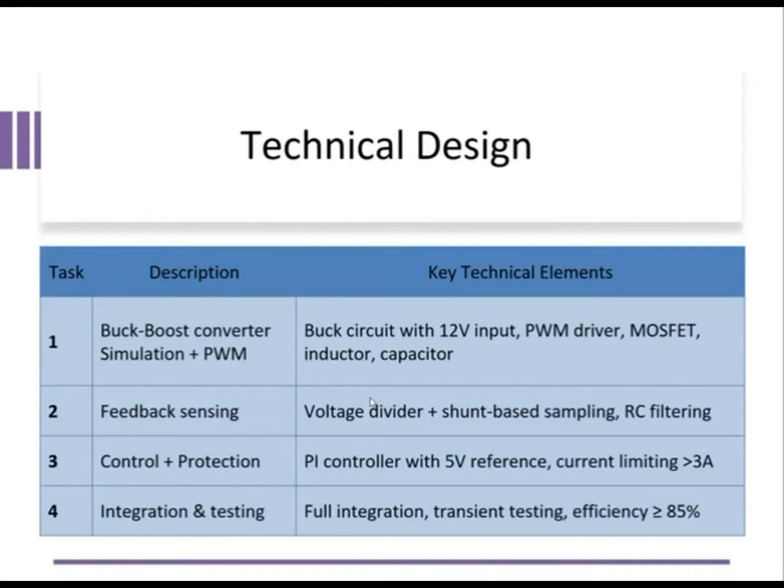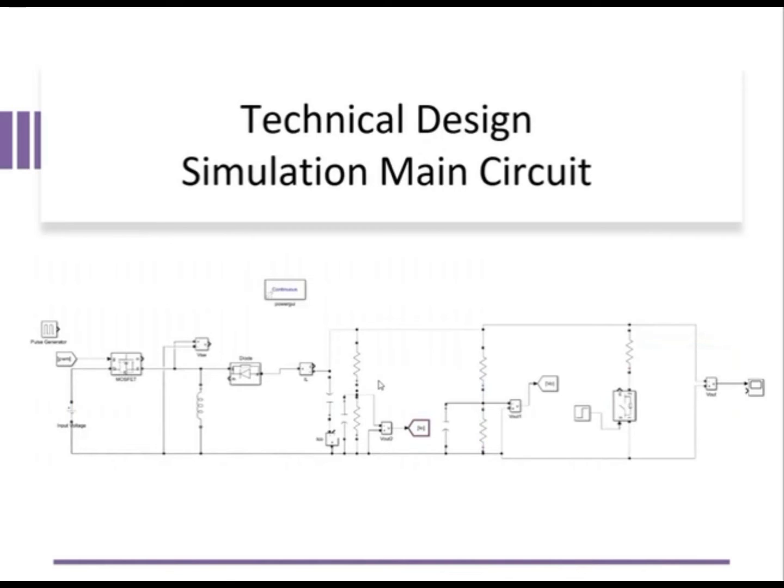Next, the technical design. I've divided into 4 tasks. I'm in charge of the buck boost converter simulation, which consists of input, PWM driver, MOSFET, inductor, and a capacitor. The PWM driver controls the switching of the MOSFET, and the inductor and the capacitor work together to achieve voltage conversion, which is the foundation for the entire circuit's operation.